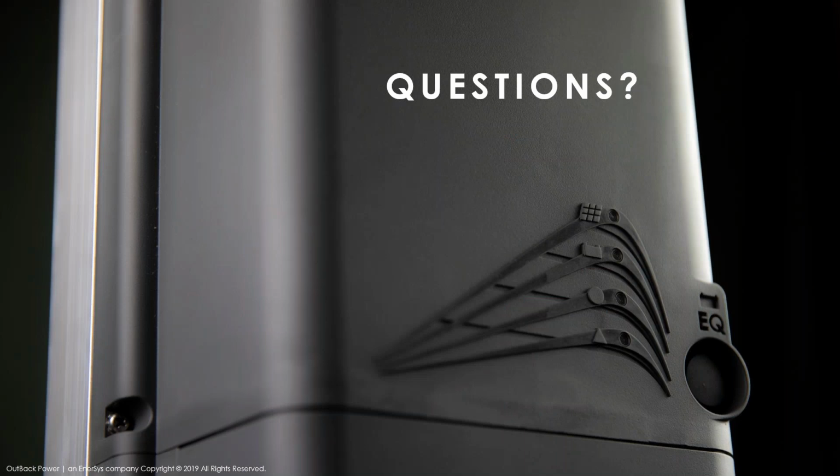All right, so we only have 5 minutes left, and I see one more question just came in here. Is it possible to exceed the 7 kilowatts mark if the VOC is below the max? I wish I could say yes, but not within warranty. The 7,000 watts is our warranty limit. Anything over 7,000 watts, in most environments, you're really risking over voltage, and that can cause pretty immediate and irreparable damage. So we are only warrantying up to 7,000 watts of PV connected to a single charge controller. But you can always stack up to 10 if you need more PV energy.